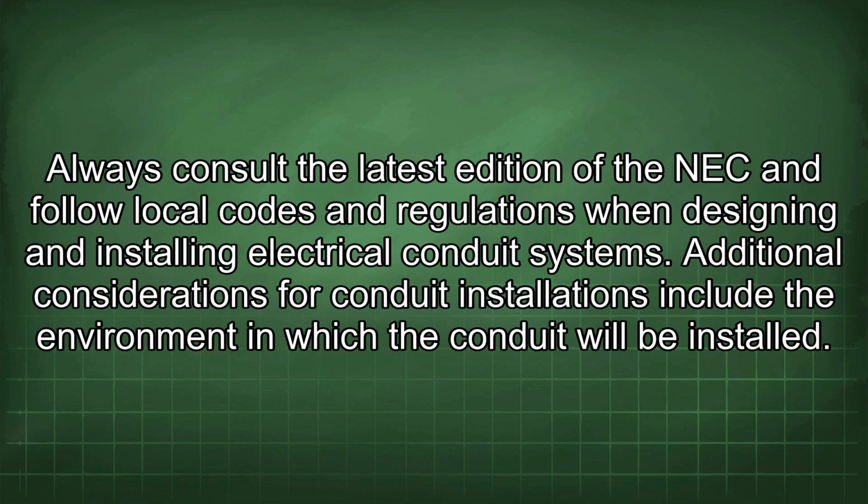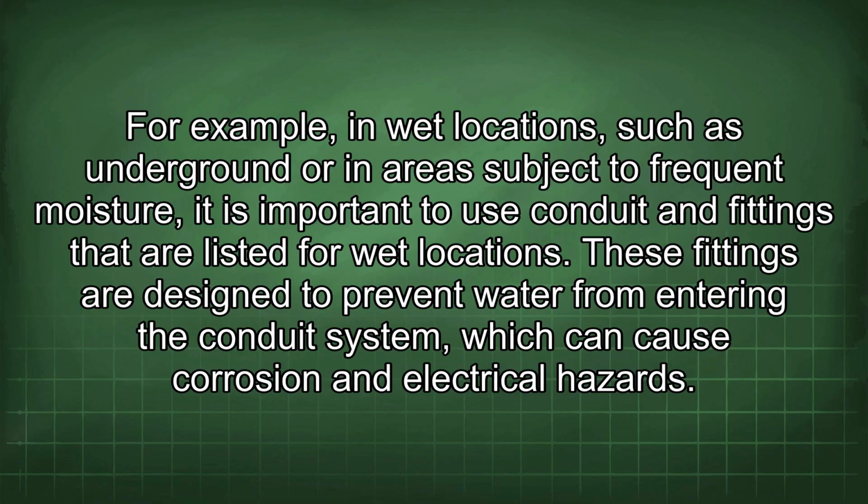systems. Additional considerations for conduit installations include the environment in which the conduit will be installed. For example, in wet locations, such as underground or in areas subject to frequent moisture, it is important to use conduit and fittings that are listed for wet locations. These fittings are designed to prevent water from entering the conduit system, which can cause corrosion and electrical hazards.